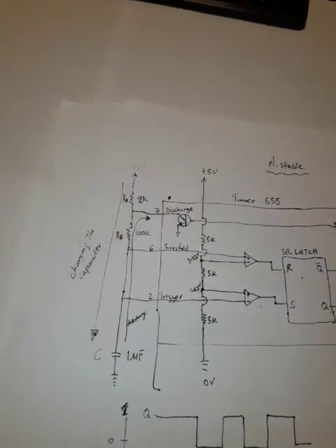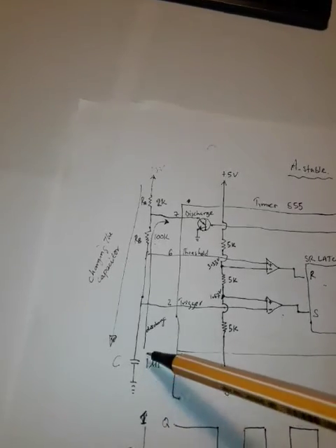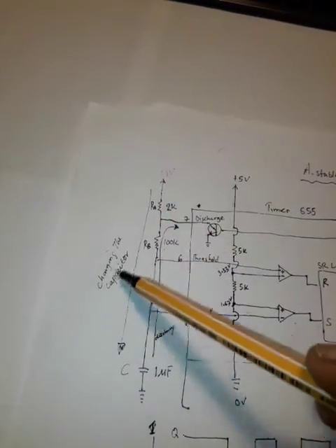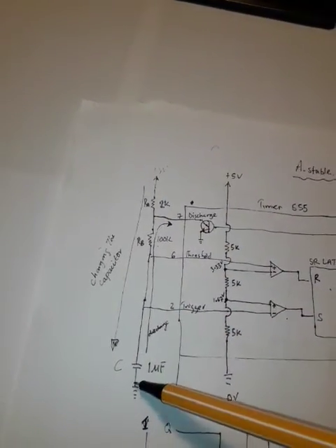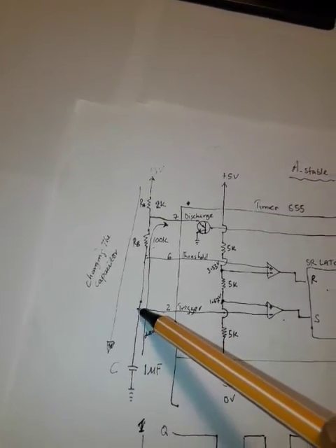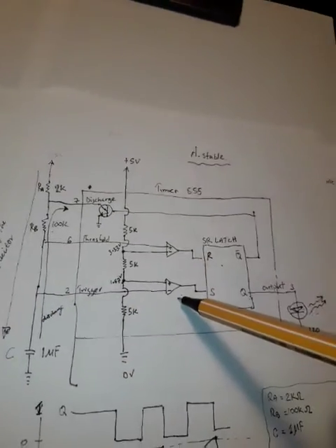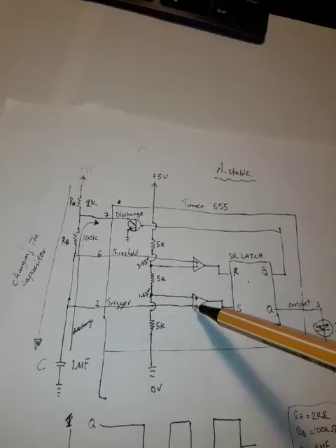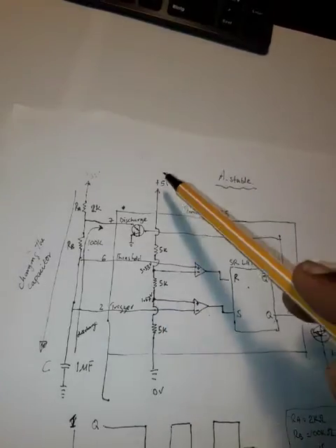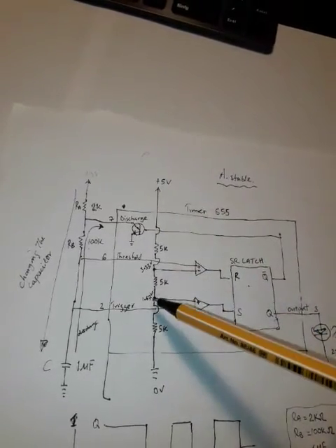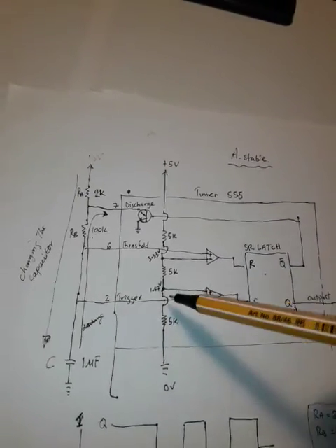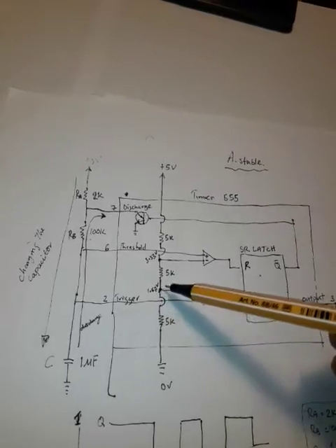And what's really happening here is you have this capacitor here, which at this point is charging because you have 5 volts coming in, and the capacitor is unable to produce charge at this time, so you have 0 volts at this point going into the comparator. But because the voltage at this point is 1.67, as we know, the 5 volts is divided into 3, so this is 1/3, this is 2/3, and then you have the 5 volt at the top. So at this point you have 0, which is less than 1.67.